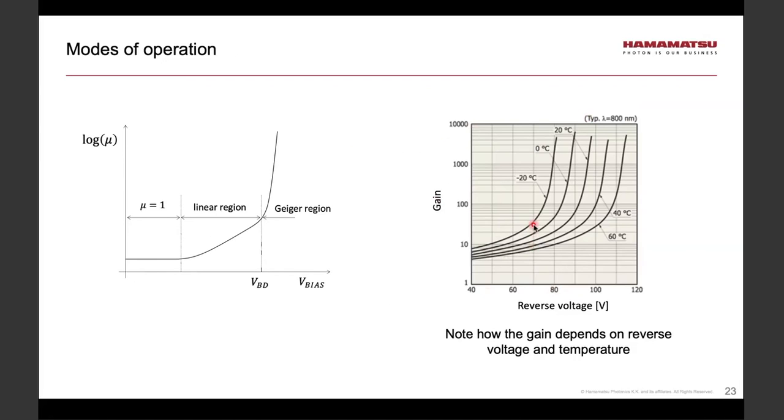That change in gain with temperature is going to lead to increased noise, especially if you don't know that temperature changes, then the output is going to simply vary with temperature. To prevent that, one can do two things: either stabilize the temperature or use a circuitry known as temperature compensation circuitry, which will keep the gain fixed even though temperature changes.